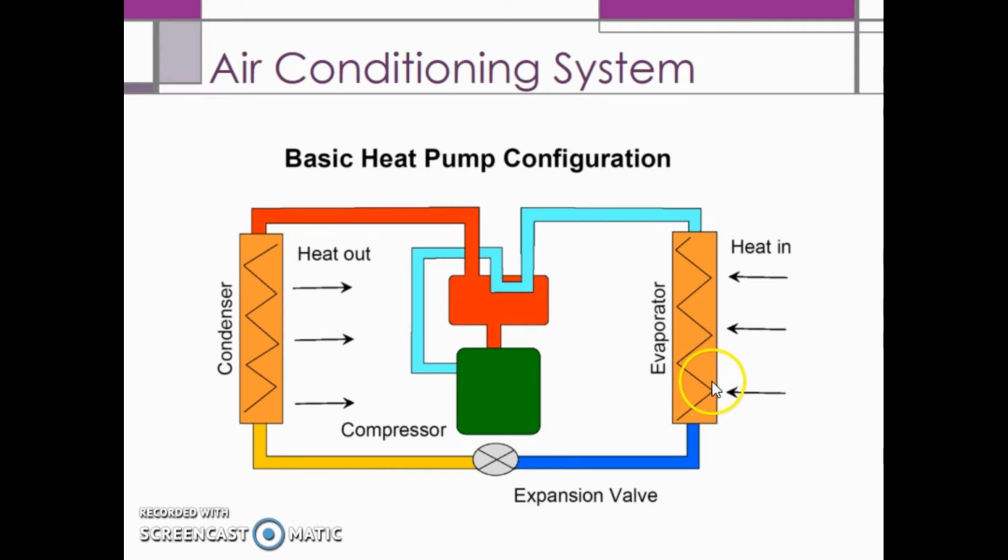This heat pump acts as an air conditioner if you are using the evaporator side to absorb heat. This means you are transferring heat from inside the car to outside the car. However, it is considered a heater or a heat pump if you are using the condenser to transfer heat from outside the car, or really the engine, to inside the car.